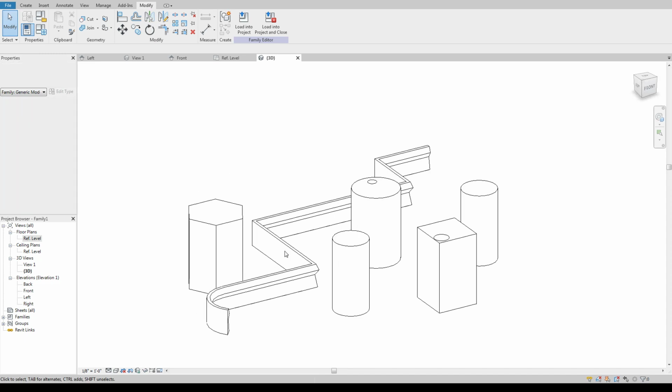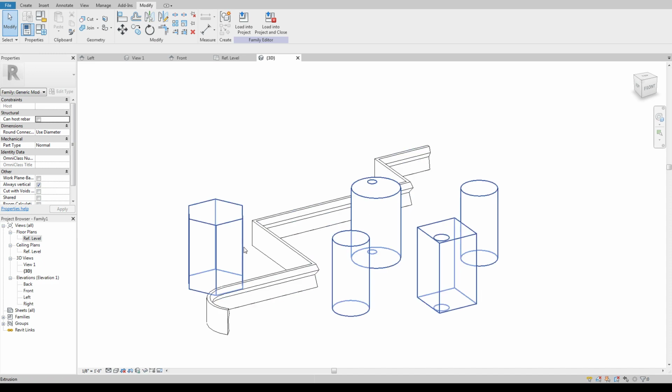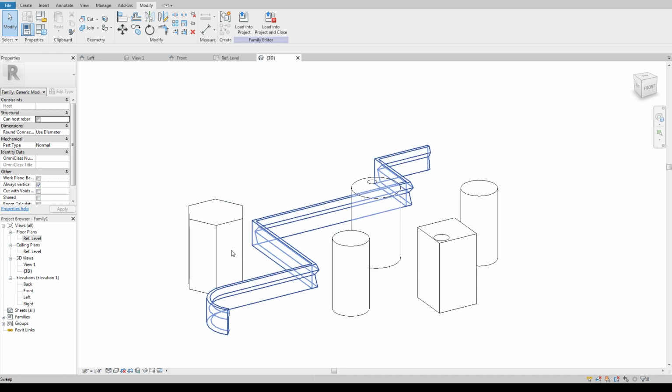So this is great for things like moldings, baseboards, casings, things that have the same profile that are running that kind of path. It's also great for turning corners and doing three-dimensional stuff in multiple planes. So right now we just created an extrusion that is in basically kind of 2 dimensions. We drew a path that was just along the reference plane, so our level. So that entire path is all in 2 dimensions. It's just moving this direction and this direction. It's not moving vertically as well.